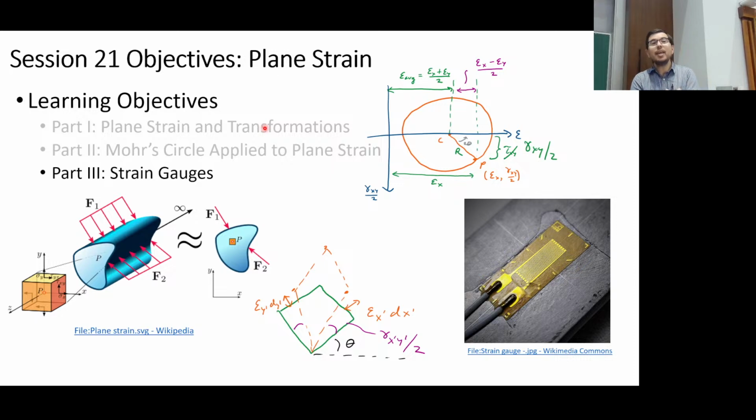So we've got two cases: bending, right? Beams, plates, whatever they're bending, their stresses are the highest or the minimums, depending on tension or compression, at the surfaces. Shear stress and shear strain are going to be highest at the surfaces under twisting. And axial loading, for many intents and purposes, is kind of uniform, right?